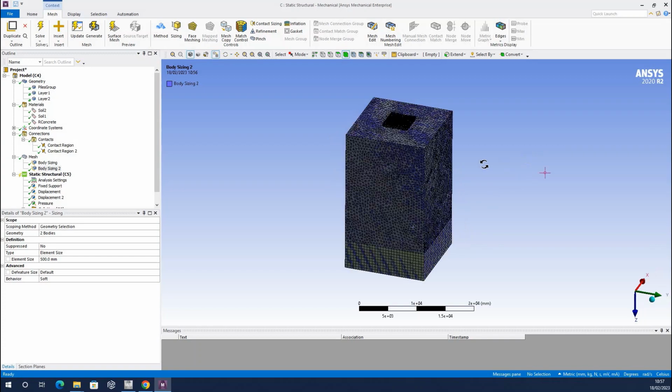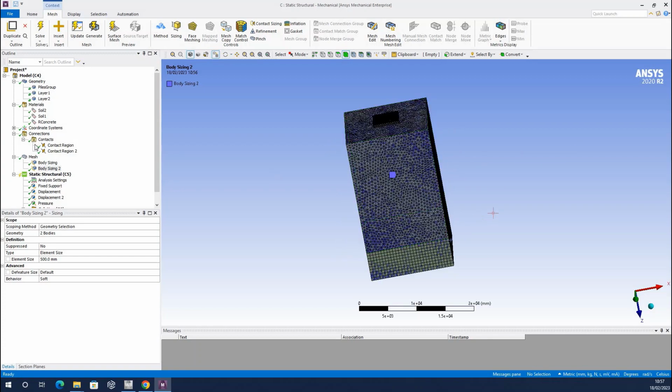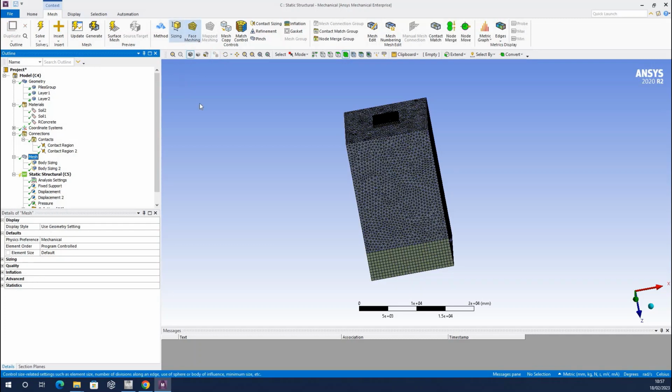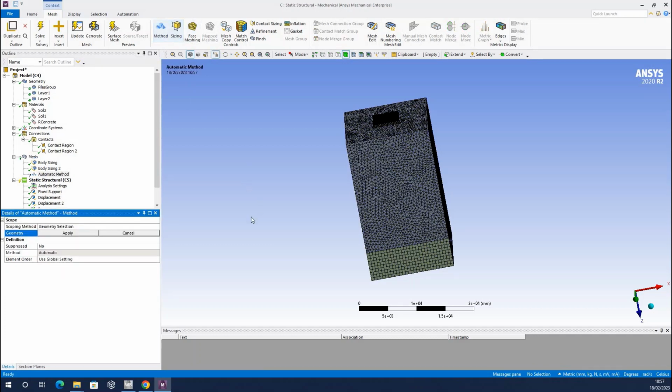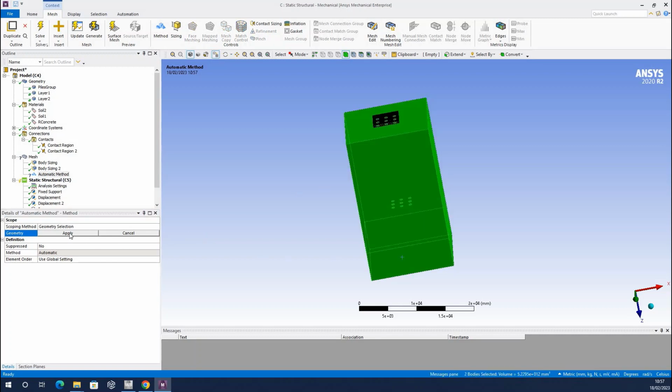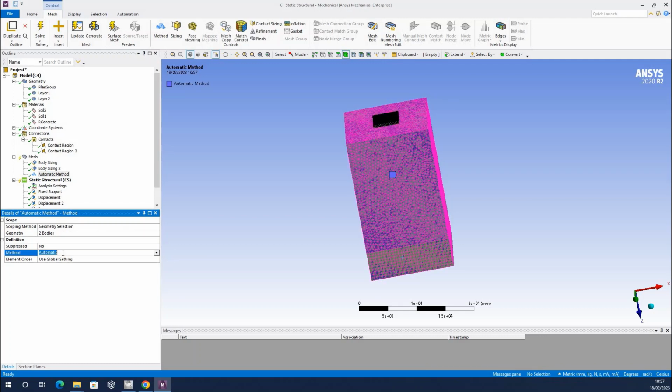So, continuing improving the mesh, what I'm going to do now is introduce another control of the mesh, and I will basically set the method for meshing, because at the moment the software has full control of the method used. So I will introduce this control in these two layers of soils, and instead of allowing the software to decide by itself what to do in terms of the method applied, I will say that I want tetrahedrons everywhere to have a consistent mesh. So I will generate again the mesh to see what I got after this control being set.